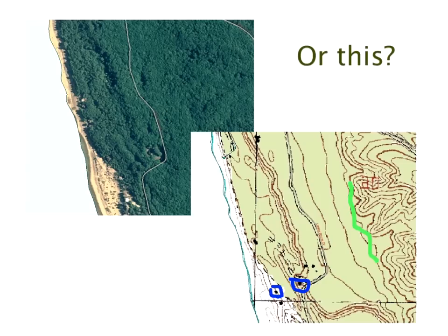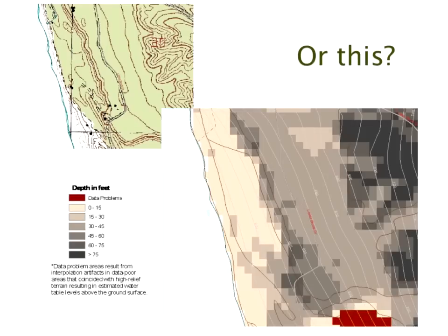Starting all the way down the Pacific coast, where I live, in British Columbia, where we have a lot of systems in British Columbia and the islands of British Columbia, all the way down through Washington, Oregon, and California, there is a large number of systems along the coast. And because of the rapid absorption of the fecal coliforms from the drip system, if it's correctly designed, there's no limitation on the ability to handle slopes and wooded areas. There's no limitation on how to do it.